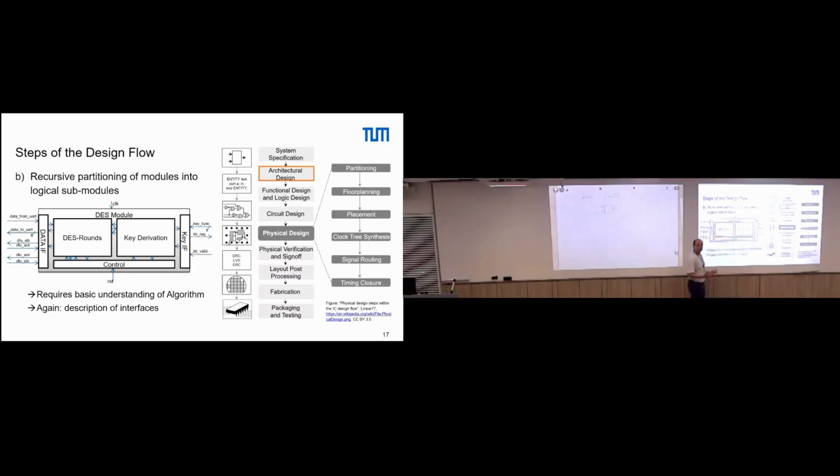And then we have on top, in the other direction, the interface to the key. So this block obviously also has an interface, and we have to define how this works. In this submodule, we have further submodules. We have, for instance, the DES rounds, which are logic functions that do permutation stuff like that, just logic operations on the inputs. There is a part which does key derivation, as it's called. It does logic operations on the key for every round. So that is a multiple round thing.